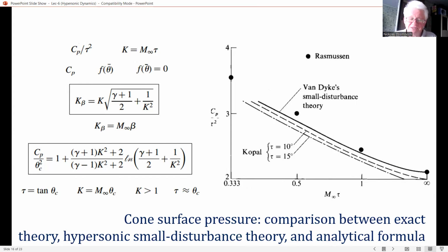Moreover, for certain optimization studies of hypersonic vehicles using the calculus of variations, a closed form expression for Cp is absolutely necessary. And therefore, we will end this module by discussing such closed form results, and thus illustrating one of the most useful advantages of hypersonic small disturbance theory.